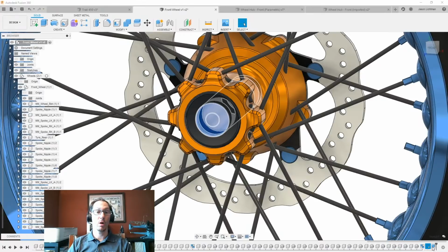But if I didn't want that history, I just wanted to be able to make that hole in that particular part without the history, I can still do that. The key is identifying which of those base features is the one you need to edit. Because you saw on my screen, and you could still see it now, I have lots of different base features. There's a different base feature for each of your components, right? Or each of your objects or bodies. They all have a base feature.